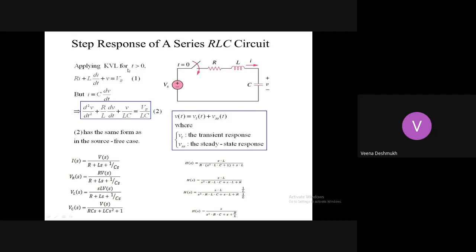So here when we take up this equation, assuming that the initial conditions are zero, that is, the initial charge on the capacitor is equal to zero, and also initially the inductor is not carrying any current due to its earlier conditions. Assuming that it is a fresh start, the capacitor has zero initial charge and the current carried by the inductor initially is equal to zero.